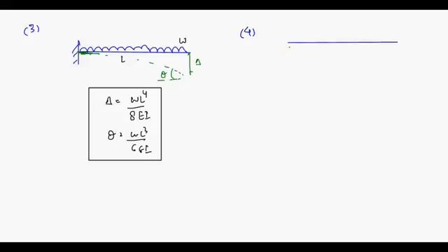Simply supported, you have a pin joint here and a roller here. Okay, and you are having a simple point load P at the center. This is L by 2 and this is also L by 2. Okay, how will it deflect? It will deflect something like this, isn't it? Here you will have maximum deflection, say delta, and this rotation is theta.